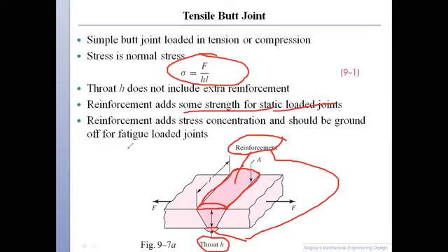But if we are using this for fatigue loading, then there is stress concentration over here, because there is a sudden change in the area. So this sudden change in area at this point causes stress concentration, and we don't want that in fatigue application. So what we do is we shave this off. We grind this off and make the surface flat over here.